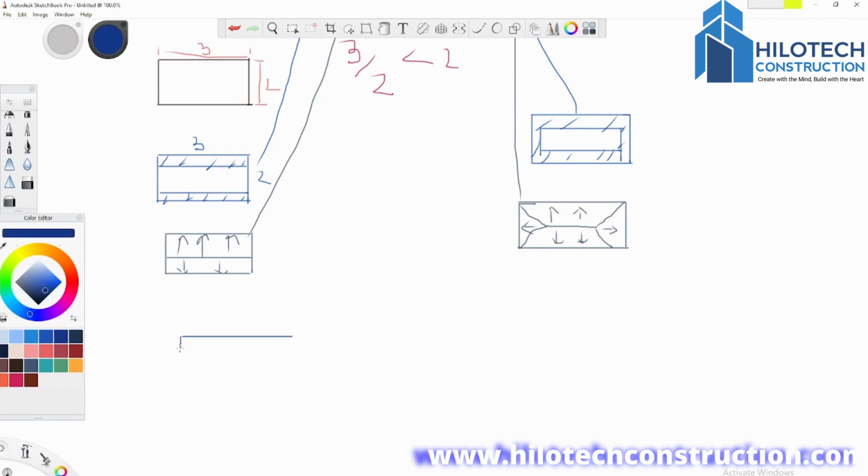In this case, I'm going to draw a section of it. It's still going to be a normal slab, but it is not being held by beams like in all the other cases that we've been looking at above. In this case, you're just going to have pillars which support the slab. So this is called a flat slab. Again, you have your slab which just rests on two or multiple columns. It depends on how you want to design it. So this is a flat slab, and here is the slab on top.